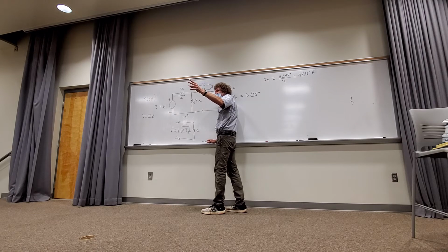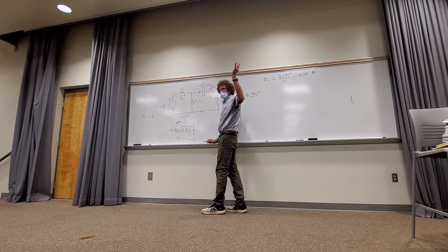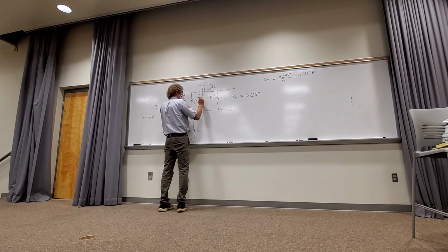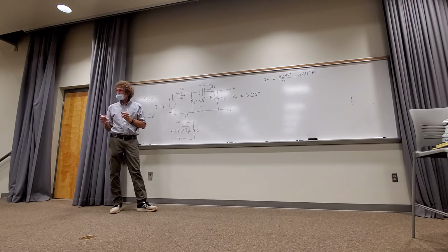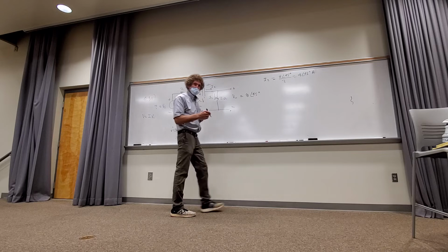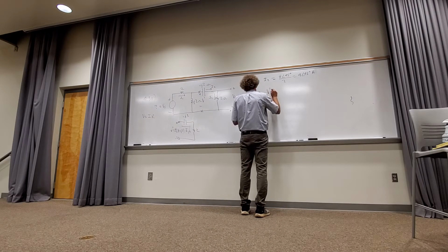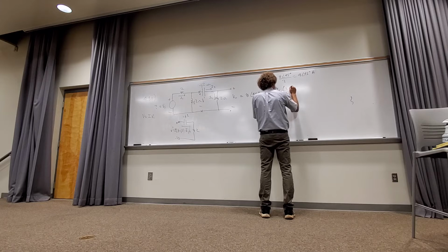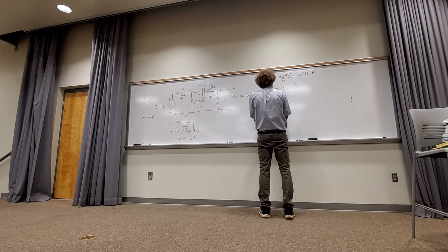You're absolutely right. I didn't want to do that one yet because it's a little more complicated. I wanted you to see that this is the voltage we could get first. Can you all see that? Show of hands, how many see we can get this voltage? You're absolutely right though. We can get V prime there. Can I call it V prime? So V prime would be equal to I2 times 2 minus j2. And I2 is that, so it's really 4 at an angle of 45 degrees.